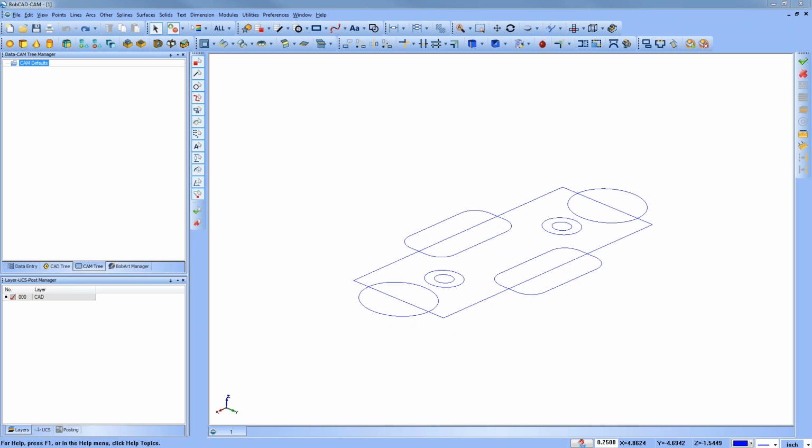What it does is it creates solid bodies by extruding closed wireframe chains or planar surfaces, and it automatically joins the intersecting or touching entities into a single solid. Okay, so what that means is, I'll show you an example here of how that works.